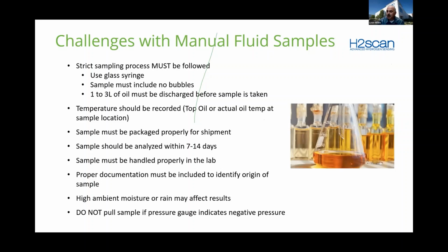Also, a very important thing that I think a lot of people don't realize is if your transformer has a nitrogen system or is a sealed transformer and has a pressure gauge, you should always check the pressure gauge to make sure that the transformer is not in vacuum or negative pressure, because you don't want to open a valve and pull a bubble into the transformer that could potentially fail the transformer,